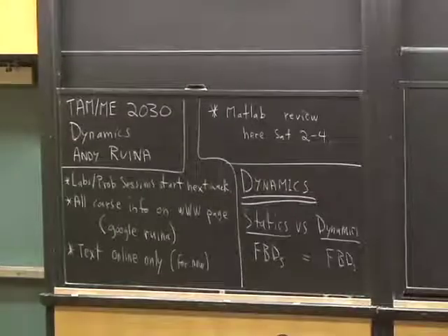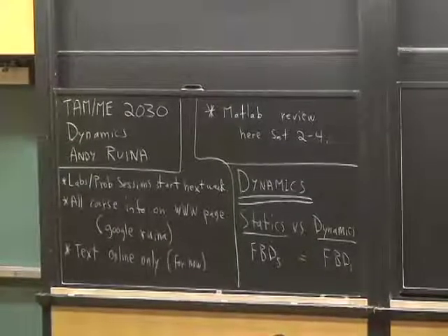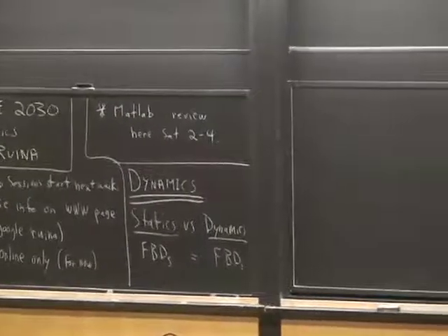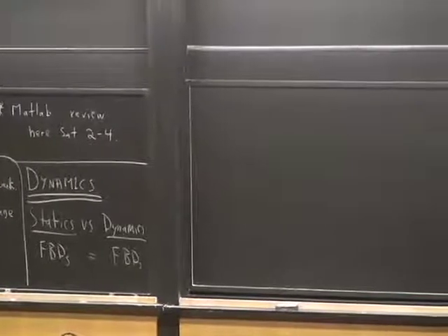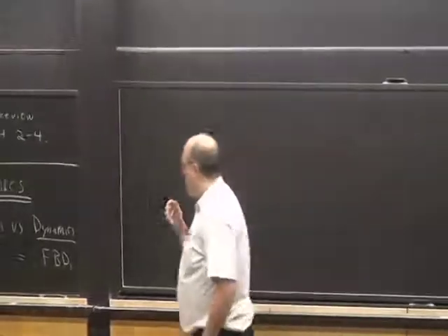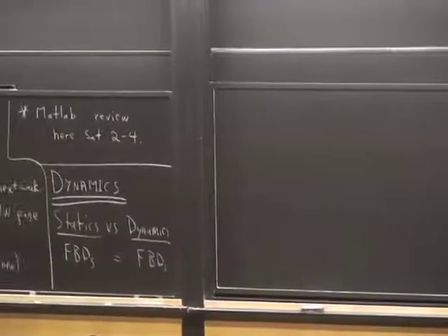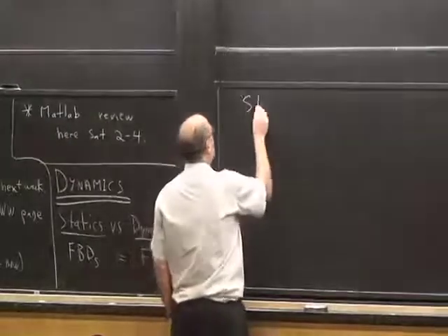Now, some people like in their dynamics free body diagrams to include something they call an inertial force or inertial reaction force or D'Alembert force. That's a different church than I subscribe to. In the church I go to, we draw the free body diagrams the same way as statics and dynamics, and we do not include so-called inertial forces.